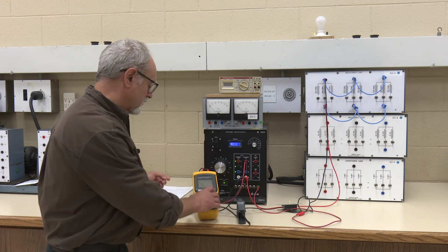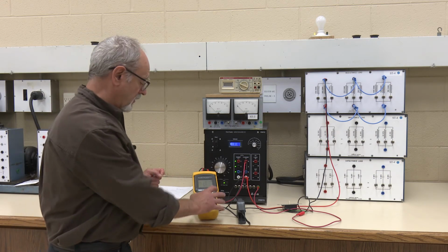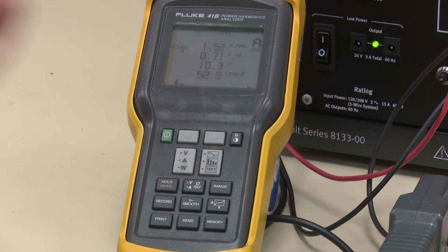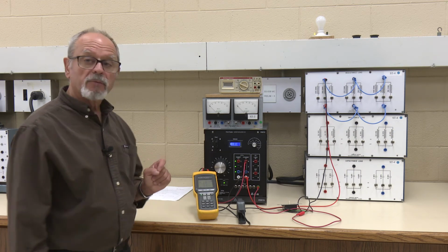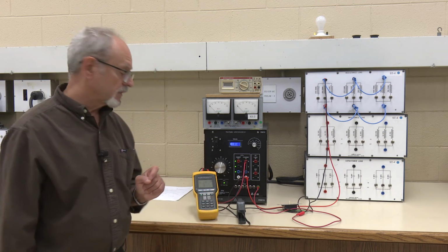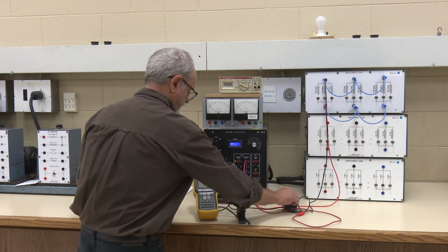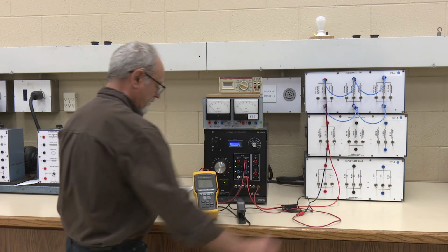And to gauge the total harmonic distortion, we go back to data, toggle to data on here. And if we just toggle over, we'll see that the percentage total harmonic distortion based on the fundamental for the current is about 53%, which again is similar to what we discussed earlier. Now what I'm going to do is more severely distort the current to 0.75 amps, half of what it is right now. And there we go.